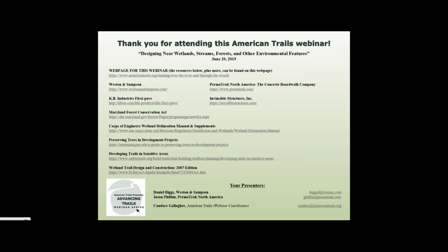Life of the structure on a timber boardwalk, I've seen anywhere from some of the coastal areas to last only 4 or 5 years, to say 15 years. 10 to 15 would be a very average lifespan for a timber boardwalk. If you're getting more than that, I'd say you're doing quite well. We have been called in to replace boardwalks as long as 1,000 feet that have been in the ground for 8 or 9 years, and they have chosen to replace it because of the reasons I just gave.